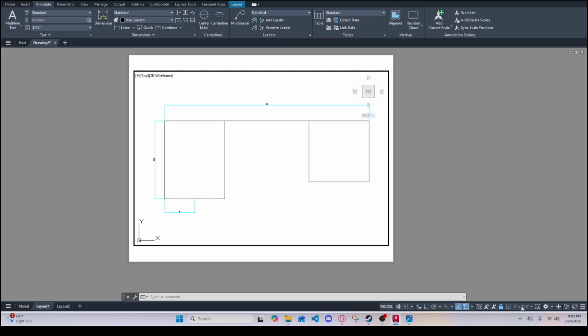and specifically your scale. If you click it and highlight the dimension lines, you can highlight everything if you want, but it's only going to really affect your dimension line, and press enter. When you actually print it out, the dimension is going to be printed to 1/8. You can get a ruler and it's going to be 1/8 text height. And it's all based off whatever you have this set to scale. But you have to make sure it's locked.